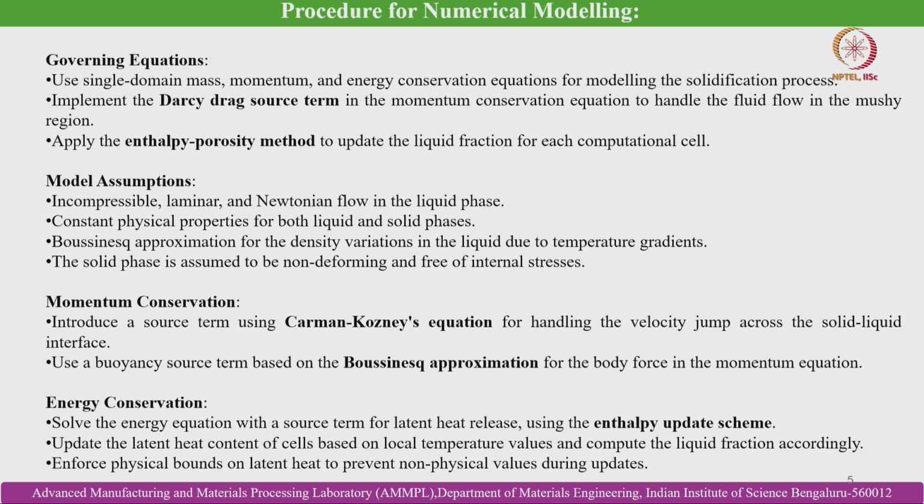That means liquid to solid transformation is in place, and the model assumptions are the fluid is incompressible, laminar and Newtonian in the liquid phase, constant physical properties for both liquid and solid phase, and Boussinesq approximation for the density variations in the liquid due to temperature gradients